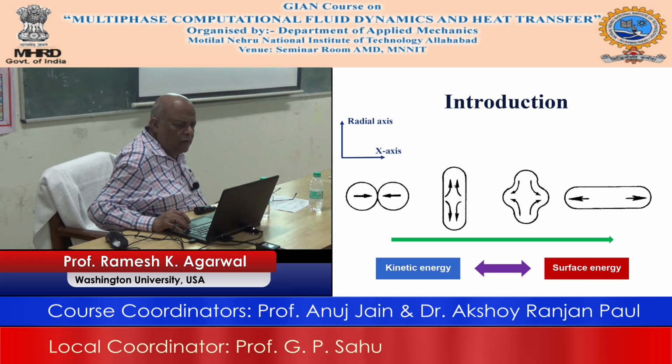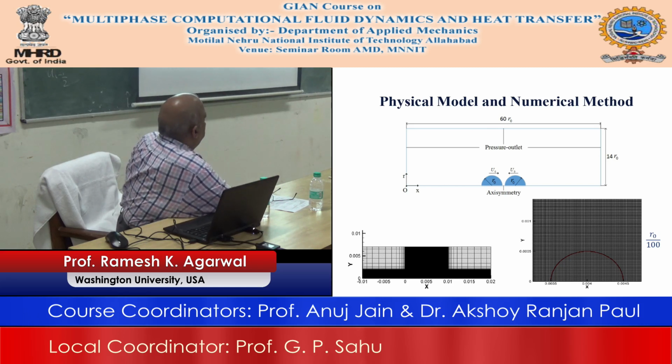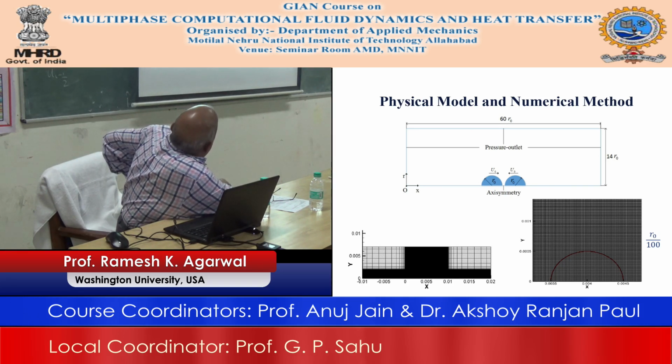So this is again the setup that you need for this droplet setup, and you again have a computational domain. We are considering axisymmetric droplets, with a symmetry line, so consider half the domain, and these are the usual boundary conditions that we have in the computational domain. Most of them are pressure outlet boundary conditions.